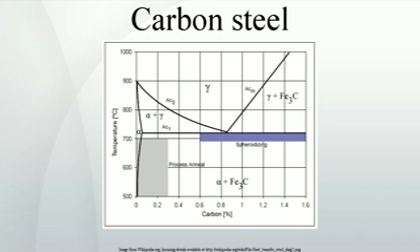The American Iron and Steel Institute defines carbon steel as the following: steel is considered to be carbon steel when no minimum content is specified or required for chromium, cobalt, molybdenum, nickel, niobium, titanium, tungsten, vanadium or zirconium, or any other element to be added to obtain a desired alloying effect. When the specified minimum for copper does not exceed 0.40%, or when the maximum content specified for any of the following elements does not exceed the percentages noted: manganese 1.65, silicon 0.60, copper 0.60.